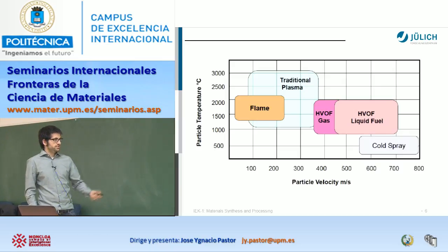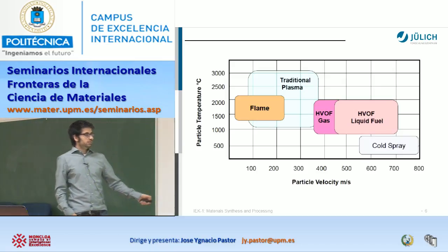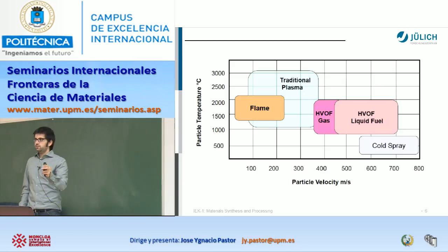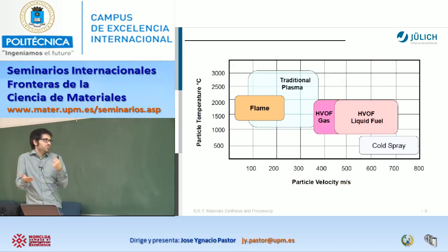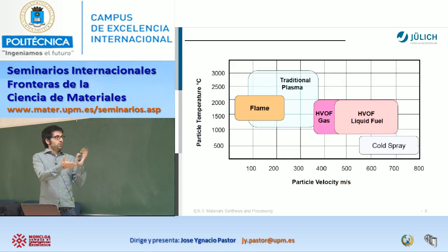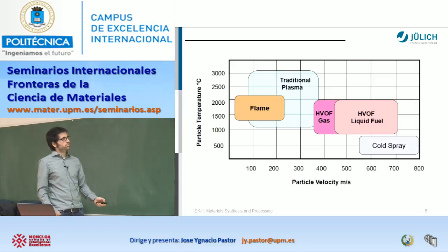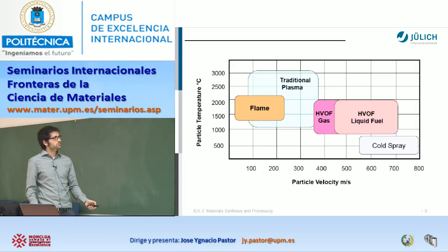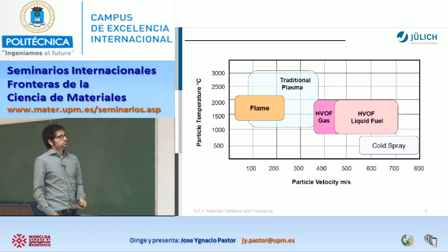And then, also really important is the velocity at which your particles impact, okay? If they are still solid, of course you just press your powder, but it's never attached, okay? And if it's too much, then it will be really liquid, and that's not good enough. Then it's a compromise, and you should think about the particle velocity and also the particle temperature, and after that you can choose your technique to do it.